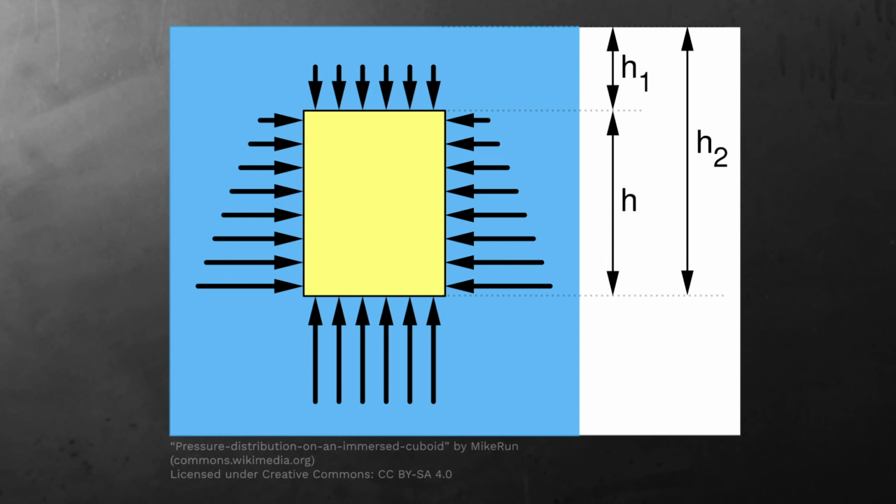Let's take a look at this to help us think about one other cool dimension of hydrostatics. What I'm showing here is a box that has been submerged in our favorite swimming pool with rectangular sides. So here's the box. If you look on the left and the right, you can see that you've got a pressure prism on both sides. There's going to be some pressure at the top where the box is under a depth of h1 from the surface down to the top of the box. And as we go down from h1 to h2, the pressure increases.